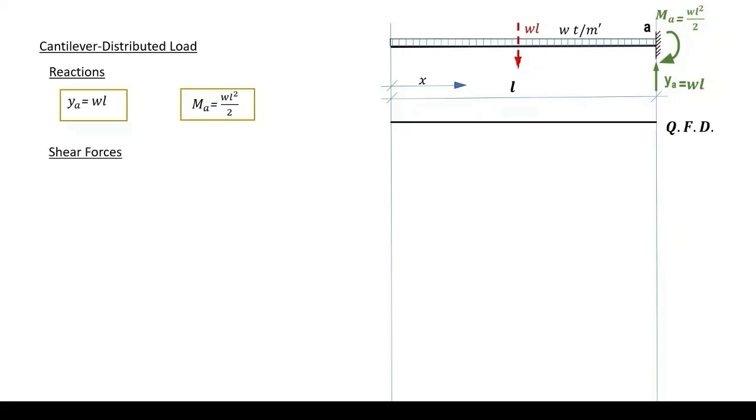Shear forces diagram. Again, take the section at X here, at a distance X from the free end of the beam. Get a section, and the shear force will be minus WX, which means the force is heading downwards.